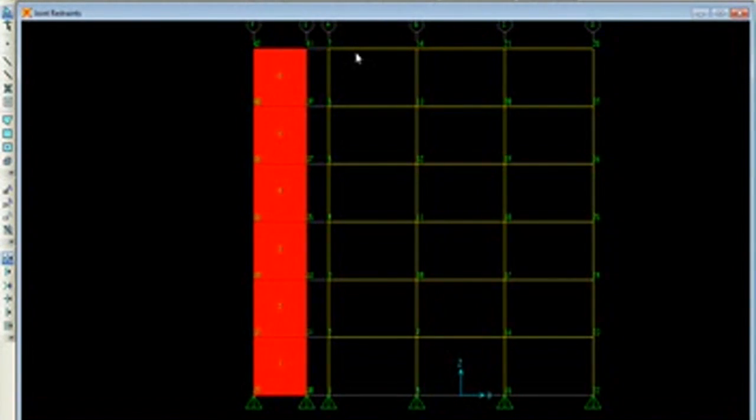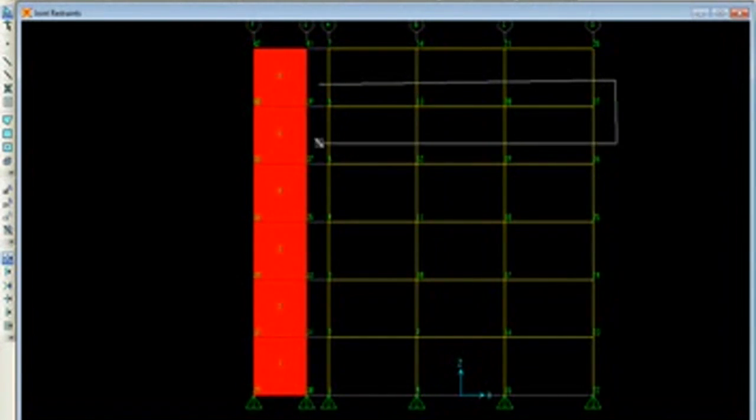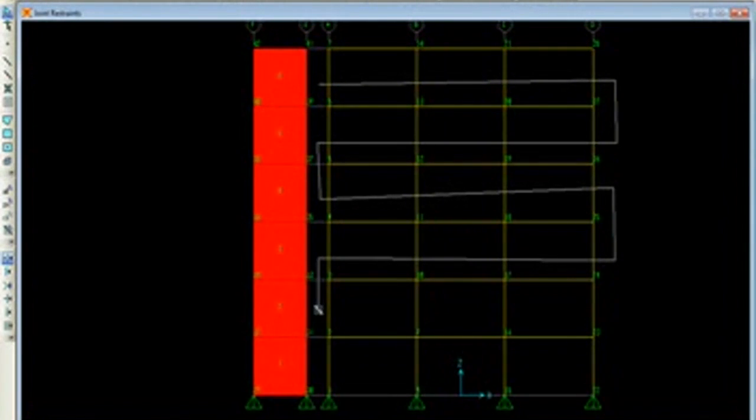So you can select the column members. You have an option of select using intersecting lines. Whatever lines this member will select, it will automatically go through. So let me say I want these columns. You can just click your left finger on the mouse, and select the column members here. Okay, so please be careful while doing this selection.